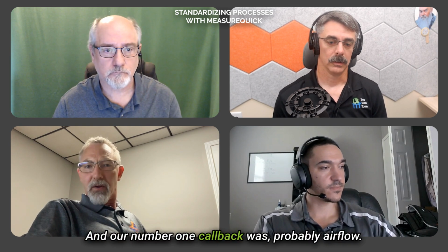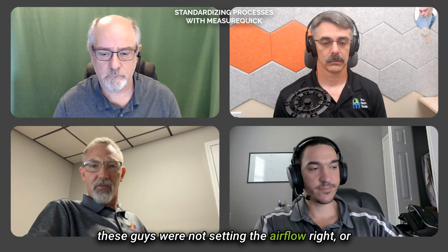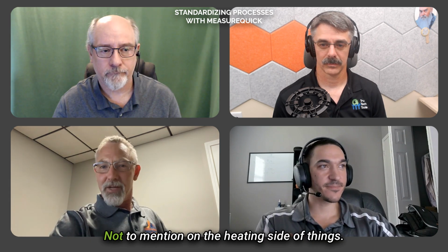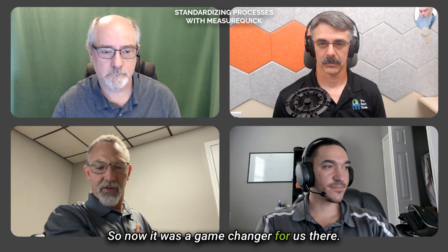And our number one callback was probably airflow. These guys were not setting the airflow right, or they were just guessing, hey, I got 20 degree split, I'm good. And they walk away. You have a calibrated hand that tells you how much airflow. So that's a problem. In the old days, we could get away with that. Now we just can't. Not to mention on the heating side of things. So it was a game changer for us there.